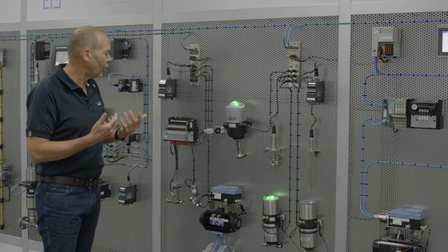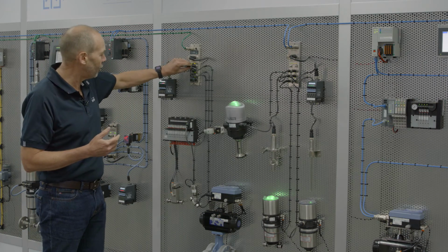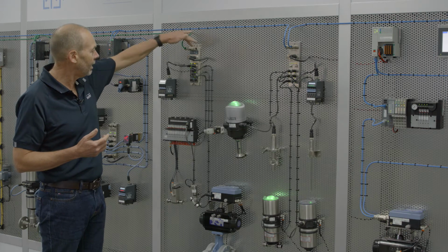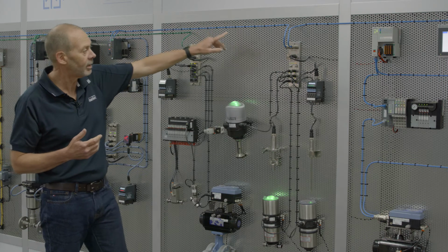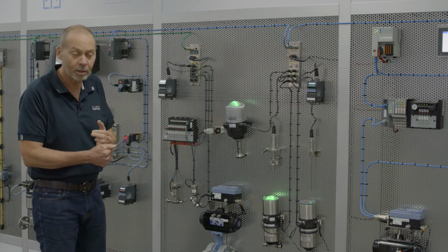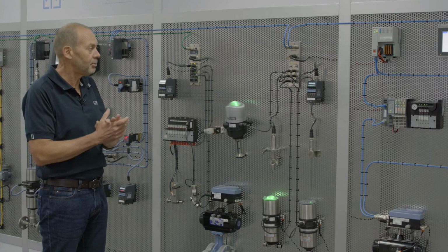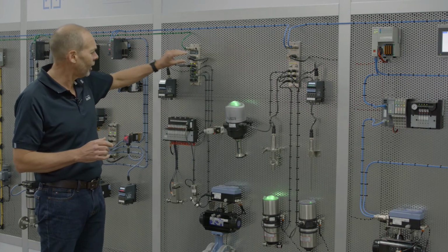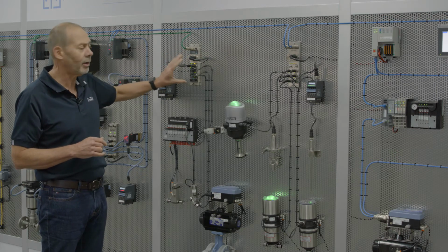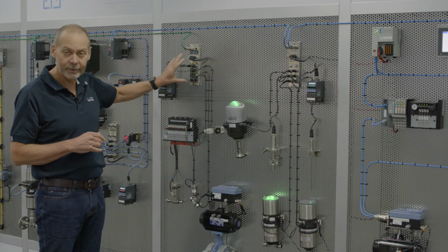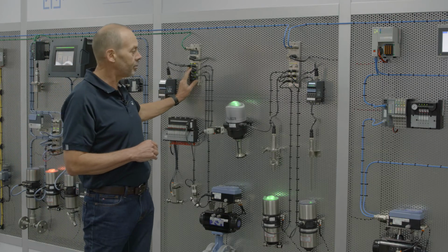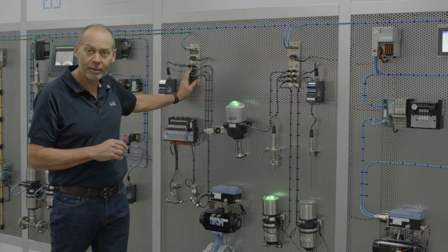A couple of the options that you can do with any of these ports: firstly, you have your Ethernet coming in and out, which means it can go onto a redundant ring topology, which makes it easy to put into the field. You have an additional power supply that can be brought into the modules, so you've got enough power locally to be able to power whatever devices you've got installed. And both of these examples have 8 IO-Link ports.